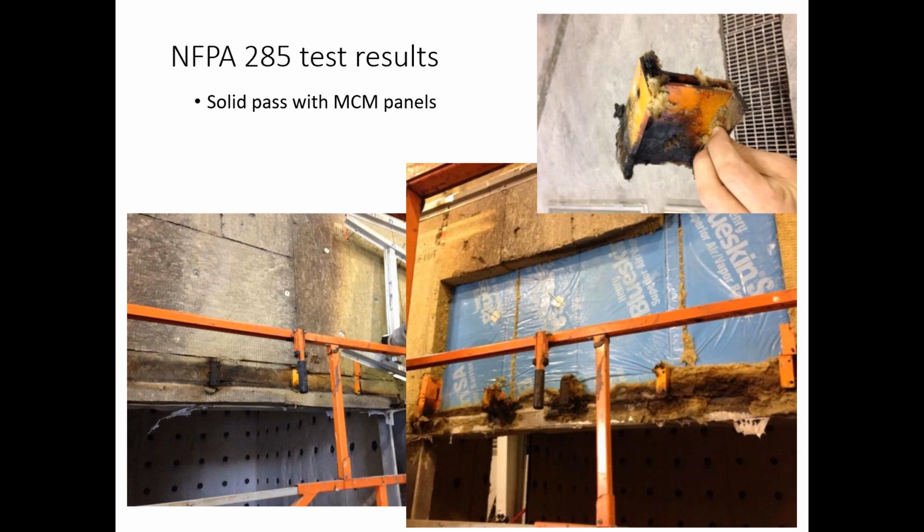It's very interesting to note how much protection that mineral wool insulation, that non-combustible insulation, provides for exterior components behind it. You can see that combustible and relatively easily melted membrane is still intact, even just a couple of inches above that window. It's really well protected. You can even see the branding and the writing from the manufacturer on that membrane surface. So that mineral wool offered decent protection.